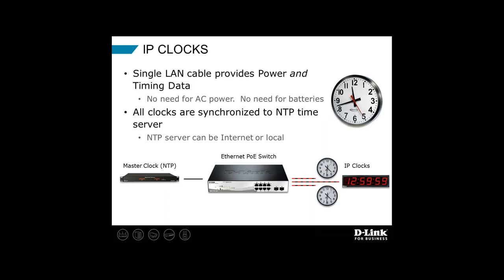Here's one that I really like, IP clocks. They can be either analog clocks, like shown here, or digital clocks. And they don't need AC power. They don't need batteries. The only input into an IP clock is an RJ45 LAN connection. So this IP clock is getting its power from PoE, and it's getting its synchronization, its data, from some NTP, network time protocol, server that's on the network. Or actually, you can synchronize with NTP servers that are out on the internet as well. So this is a really neat application.